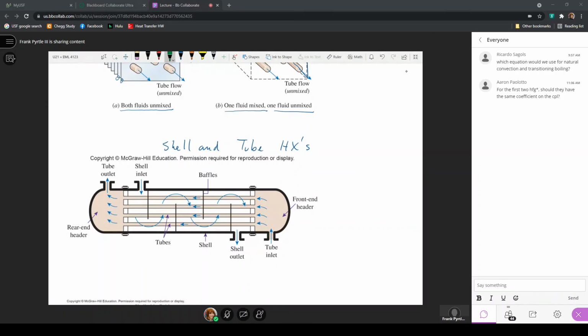The chilled water would increase slightly in temperature, and the air temperature would decrease significantly because the specific heat of water is so much higher than air. We can get a huge air temperature difference in the lowering of that air temperature, while the water only experiences a very small temperature increase because its specific heat is so high.